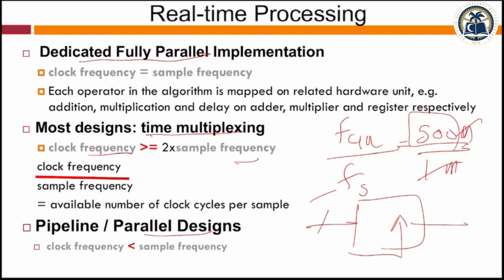500 means that there is a potential of folding the architecture 500 times. Whatever is running in Python, you can fold that architecture 500 times. Okay, so if there is an adder, you can use that adder 500 times, in the best case, because you have 500 cycles to do what is happening in your Python code. So that is important.